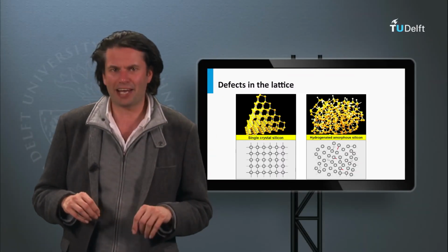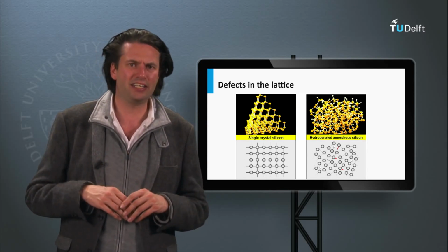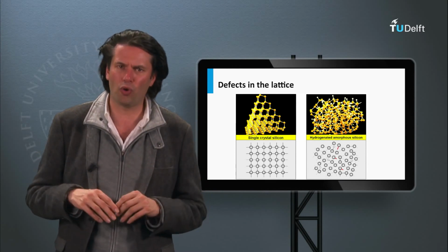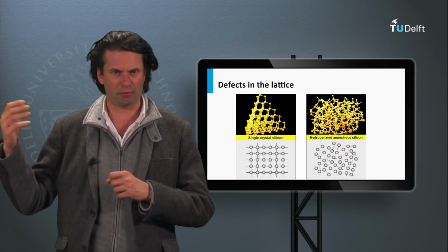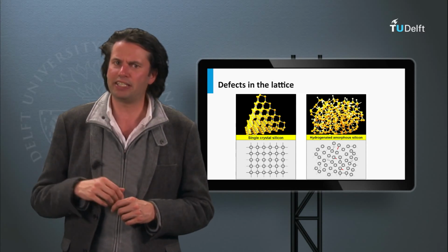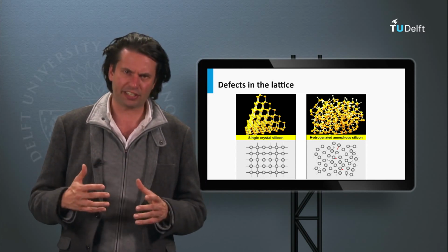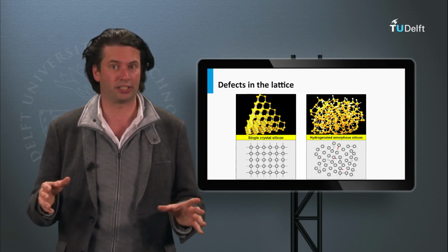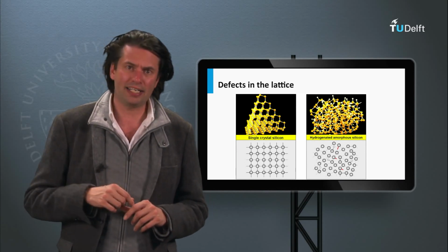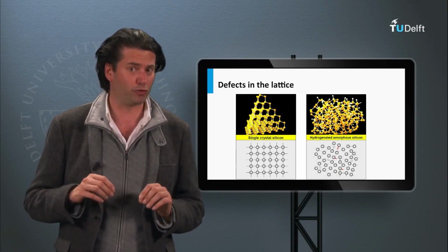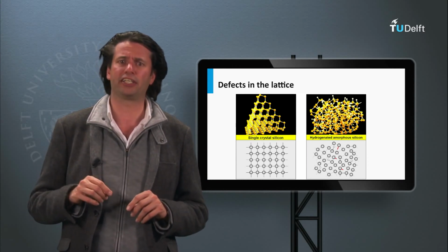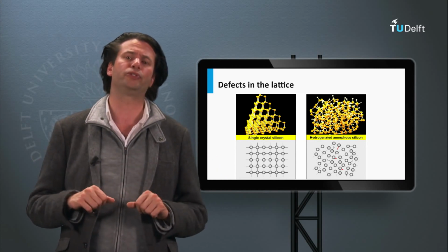The hydrogenated amorphous and nanocrystalline silicon films have a relatively high defect density in reference to crystalline silicon. Due to the disordered structure, not all valence electrons are able to make bonds with the neighboring atoms. The so-called dangling bonds can act as defects. This means that the lifetime of the light-excited charge carriers is limited by the Shockley-Read-Hall recombination, which controls the diffusion length. The recombination is so high that the diffusion length of the charge carriers in hydrogenated amorphous silicon is only 100 up to 300 nanometers. This means that the transport of charge carriers in a thick absorber layer cannot rely on diffusion.